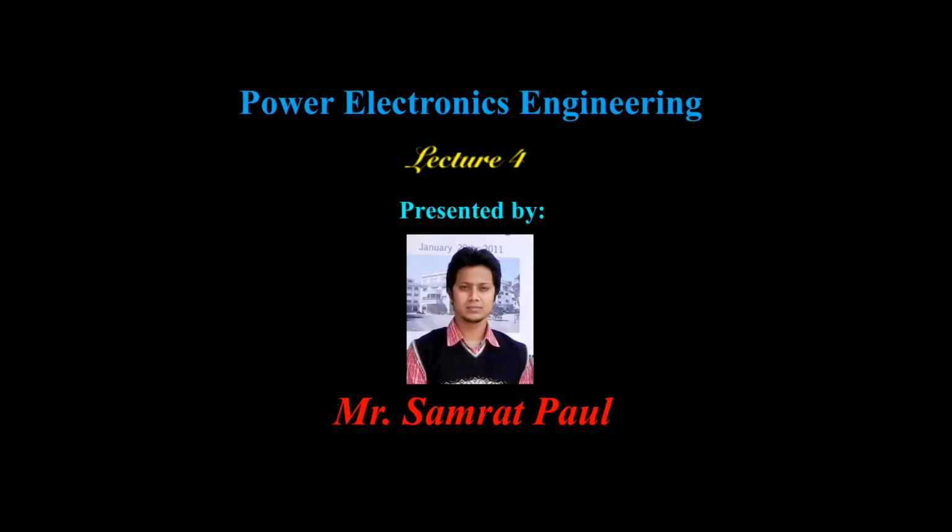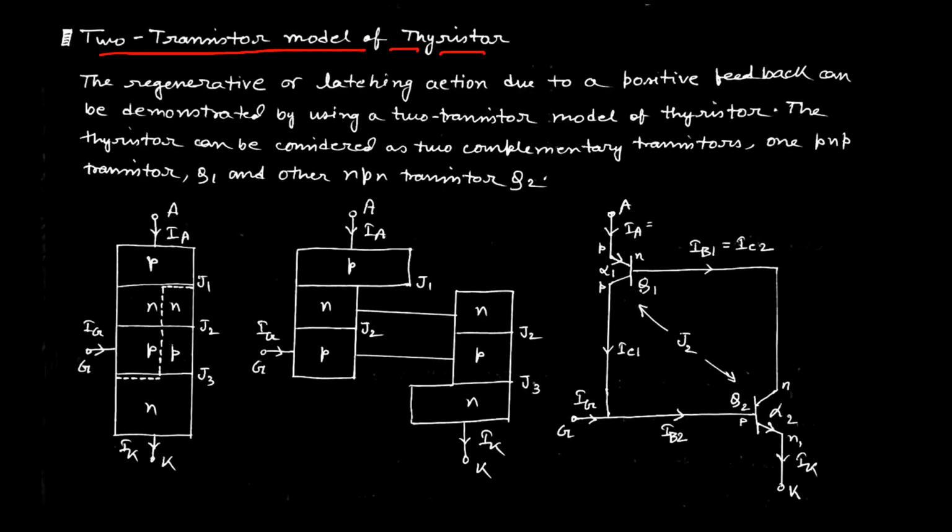In this lecture session 4, I am going to demonstrate the topic on the two transistor model of Thyristor. That means we are going to present the turn-on process of Thyristor by using the two transistor model. Here we consider the structure of the two transistor model of Thyristor as well as the schematic diagram of the two transistor model. The regenerative or latching action due to a positive feedback can be demonstrated by using a two transistor